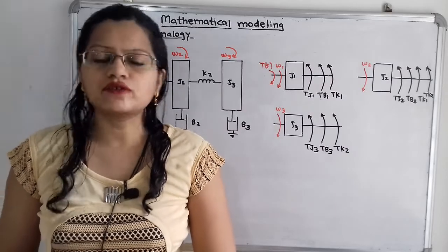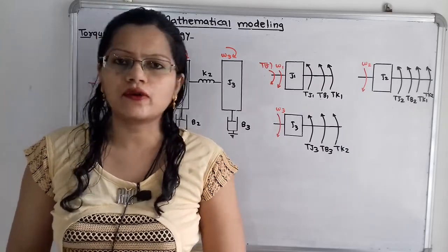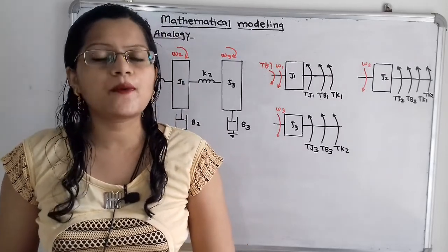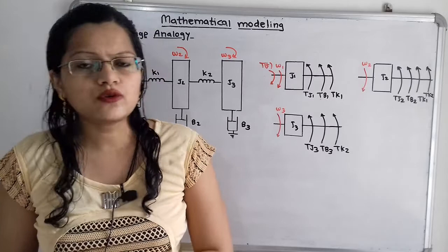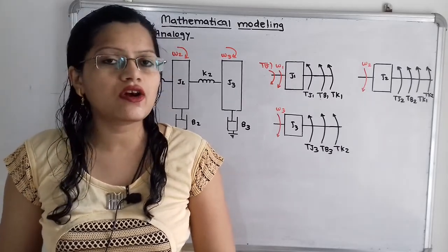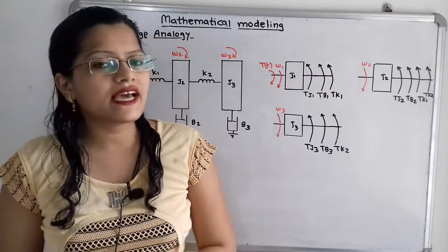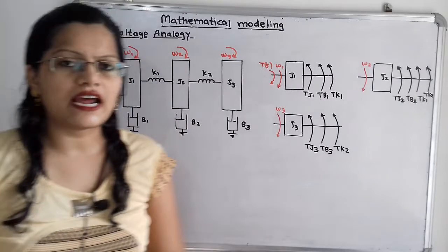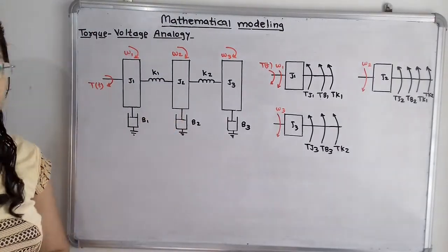Today we are going to solve a problem on torque voltage analogy. In this video, I will give you some important tips regarding how to apply torque voltage analogy and how to draw analogous electric circuit with the help of differential equations. Let us first understand what is the given mechanical system.